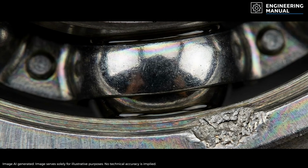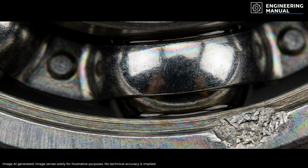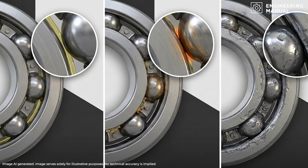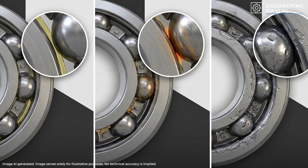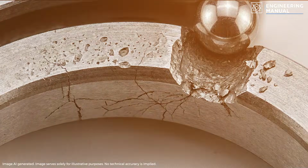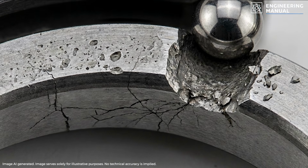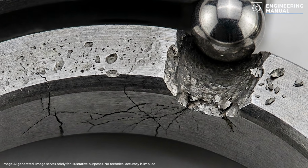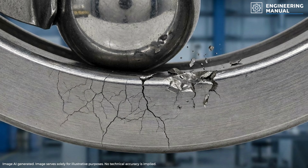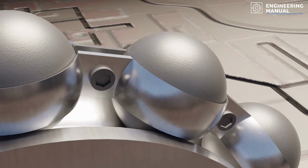The steel survives only because both the balls and raceways are hardened to exceptional strength, while a microscopic oil film prevents direct metal-to-metal contact. Even then, fatigue eventually wins. Microscopic cracks form beneath the surface before slowly growing outward until pieces of the raceway begin breaking away, a failure known as spalling. Ball bearings therefore occupy a very specific place in engineering.